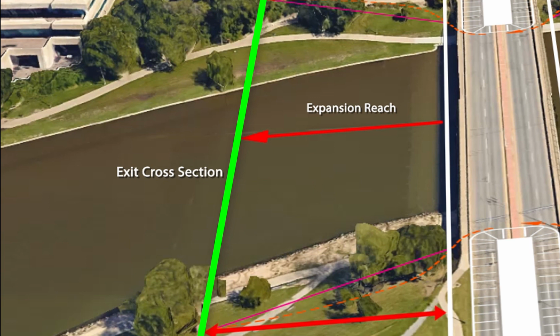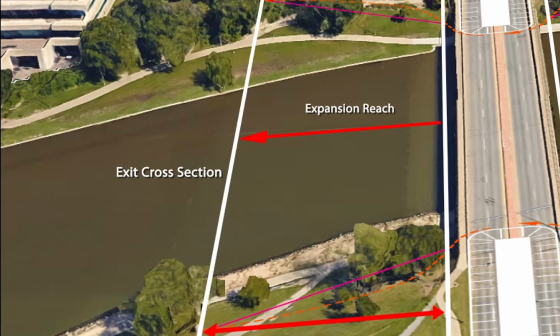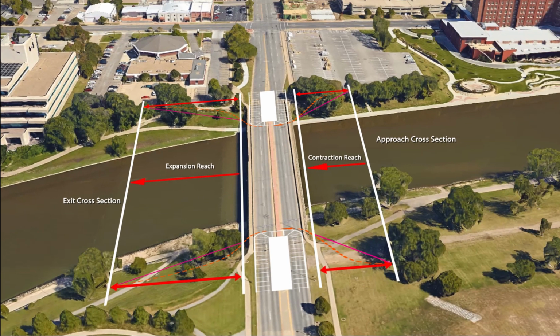Again, as I described earlier, it is where the water molecules are running parallel to each other. The distance that the exit cross-section is offset downstream from the downstream face cross-section again varies upon the site conditions. However, the rule of thumb that is typically used is that the flow contracts at a 2:1 to a 4:1 ratio. So if the overbank flow on one side of the river expands outward 100 feet, then the exit cross-section is placed between 200 and 400 feet downstream of the downstream face cross-section.